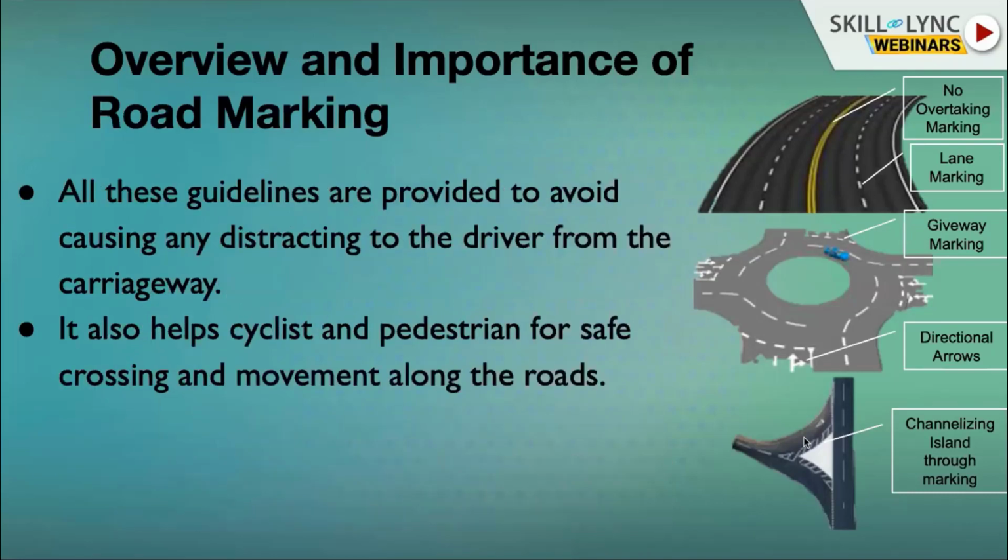Road markings are very useful tools to guide the road users, since these are placed along the travel path of the driver, and they provide guidance without distracting the driver's concentration on the road, because he need not turn or tilt his head to look at the information. Markings are provided even for the cycleway and pedestrian guidance as well, like zebra crossings, which are called block markings, and cycleway markings, which are provided for the dedicated cycleways.